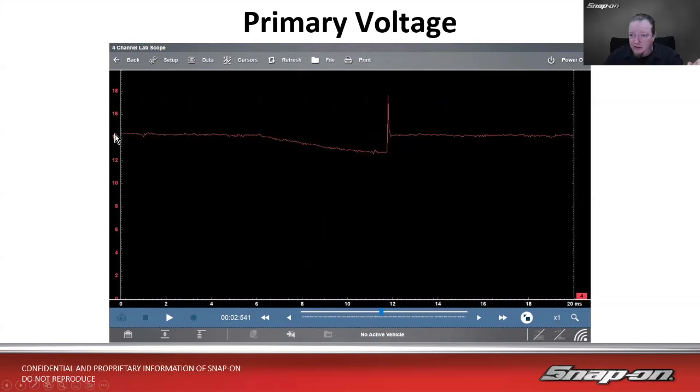So you can see the voltage comes in, 14.4, whatever. When dwell starts charging the coil, you can see it drops off. And then once it fires, you see a big spike there. It's only like a 4-volt spike, but still you'll see a spike, relatively big. And then that's where the spark line should be, but there's really not a lot of detail going on there. And then it just goes back to 14. So that's just because of the drop off with the built-in igniter and everything.